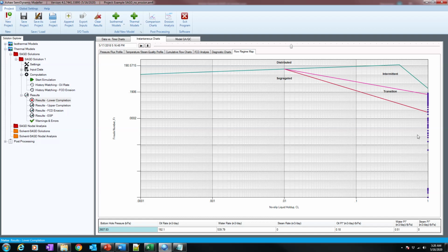And we have a flow regime. In this case, we ran the flow regime map, and it's pretty simple. Because we don't have a lot of steam, everything happens here. There is no gas liquid holdup. These are not 1, these are numbers close to 1. But because it's a log scale, everything looks like it's here. So for multi-phase modeling, we're always looking for transition zones. If something's happening here and something's passing here, we're probably shaky inside the tubing, or we have to watch the modeling even if these cases are fine.